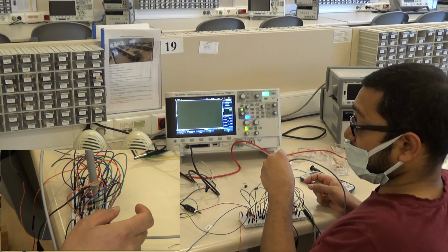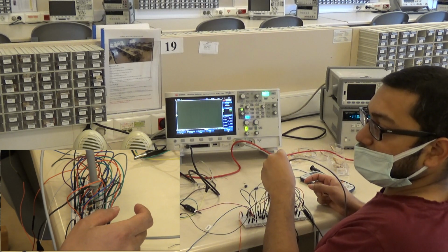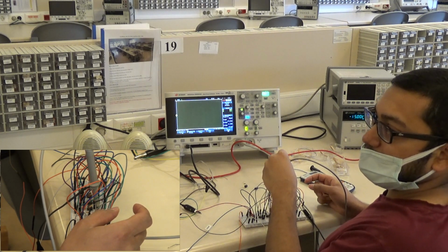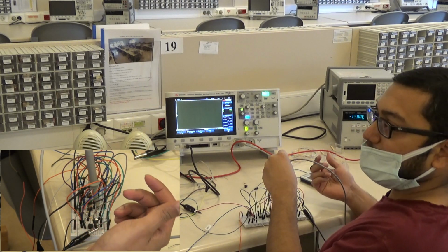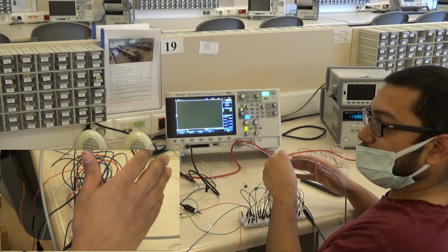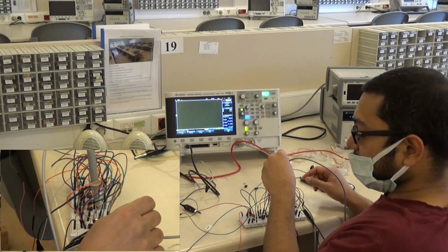Basically it's a 3-stage amplifier, but you can use any combination. You can take 2 inverting stages and then a non-inverting stage so that the phase difference is 0 degrees or 360 degrees. That's our idea.